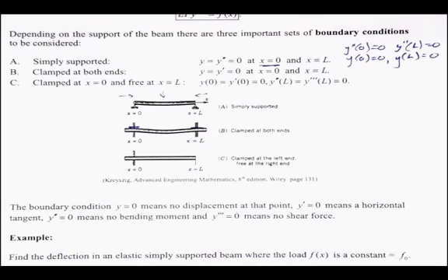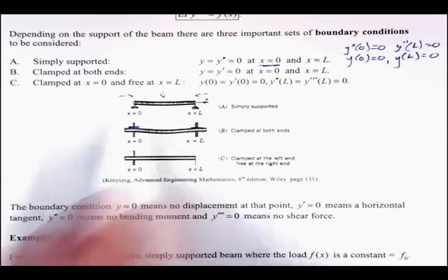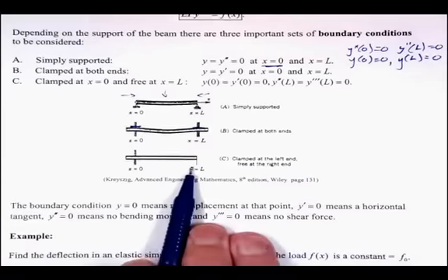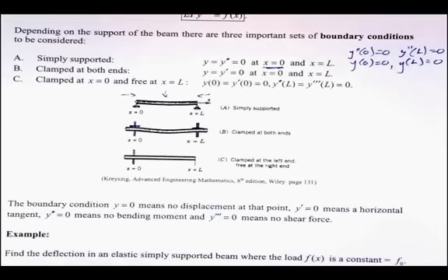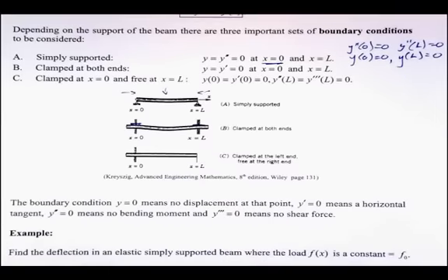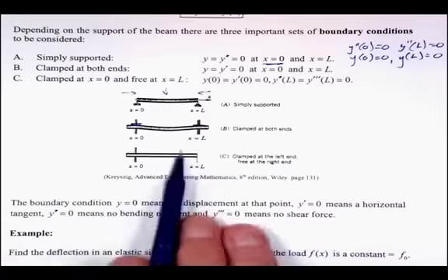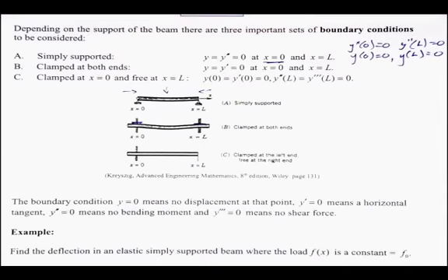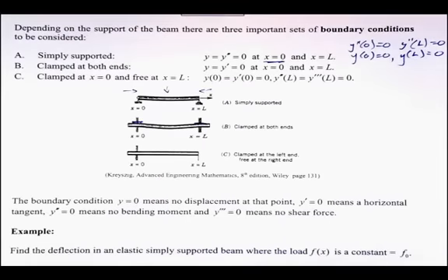Okay? Now, probably what you couldn't have is simply supported at one end and free at the other. Why not? Because the whole thing would just fall off, wouldn't it, in that case? So there are some combinations that aren't practical. But there are further extensions of this that you could have simply by making some minor changes to these details. Well, let's go ahead and solve this